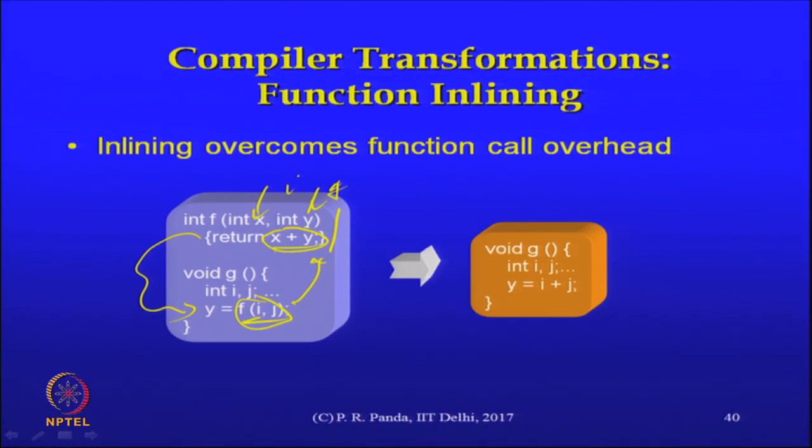We did not say how functions would be synthesized, there could be a couple of ways, but at least one way to synthesize functions would be in fact to inline all the functions. Okay, and then you just build a data flow graph for a single function and go ahead with the synthesis. The explicit idea of a stack and whatever the protocol is for a processor based design need not be respected in the synthesis, but one way is you just inline everything.